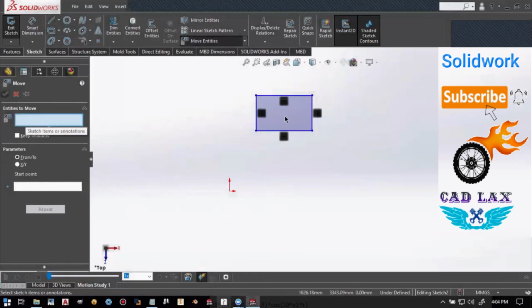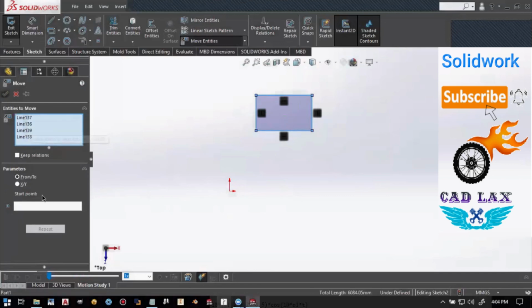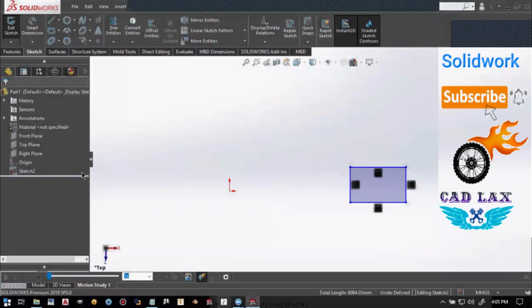Entities to move: I want to move all these four lines. So four lines are selected. There are two options to move the sketch. First one, we can move it according to the coordinate system. If you want to move it according to the coordinate system, you have to click on this X and Y. So we can put the delta X value and delta Y for this object. Another one is From-To. So you have to select a base point and the final point where you want to put it. Simple. Next one is copy.